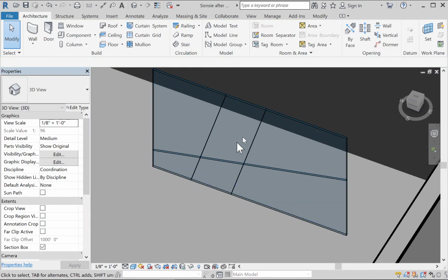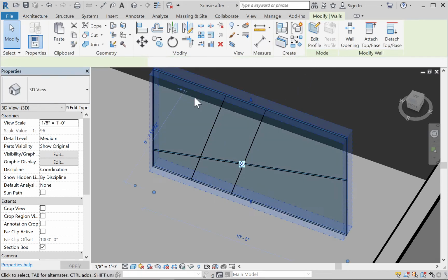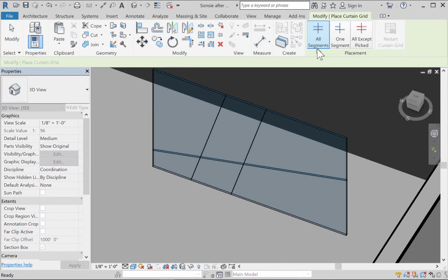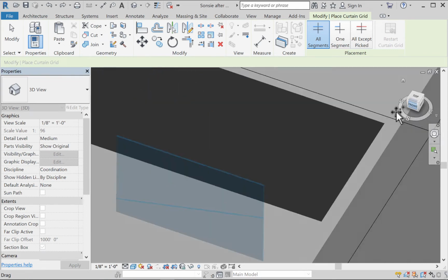If you get more than one mullion, though, each new one is going to come in basically the same way. If I come in here and go curtain grid and try and draw a horizontal one, it's going to draw another one parallel to the first one. So for you super advanced students who want to show off your skills, there's really only one way that I know to be able to get multiple grid angles out of these things.